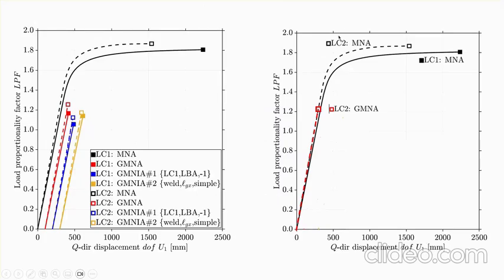Notice that the solid dashed line was load case 2, material nonlinearity only, which was tutorial 7. I did not do load case 1, which is the solid black line, but now I'm doing load case 2, geometric and material nonlinearity, and of course the software is going to run until it crashes at this point. So obviously some nonlinear stability occurs here, which is not our goal.